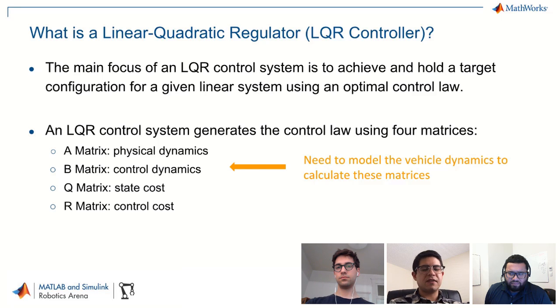That's where we specify what's the most important target or part of the state to hit. For example, for us, holding depth is really important, because if our robot ever surfaces, then we get disqualified. So the Q and R matrices basically just allow us, for lack of a better term, to tune our controller.